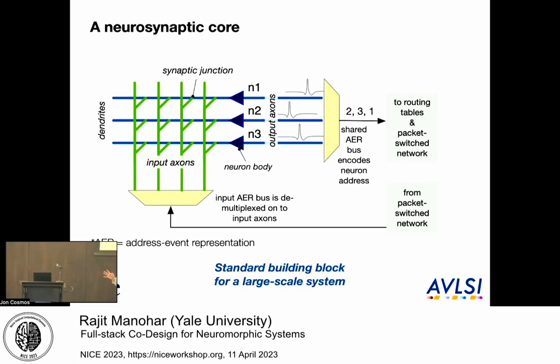And as soon as you see that, you go, well, then I'm going to do it digitally, because in 28 nanometer I know how to make that work. In 28 nanometer, making good analog electronics is a non-trivial, very high cost endeavor. So the solution is just to use digital, not because digital is necessarily better, but because its effect on the overall system is so small that other considerations come into play, like: am I likely to get a working chip the first shot? Or do I have the budget for a respin? Actually, we didn't, so we didn't really have much of a choice.